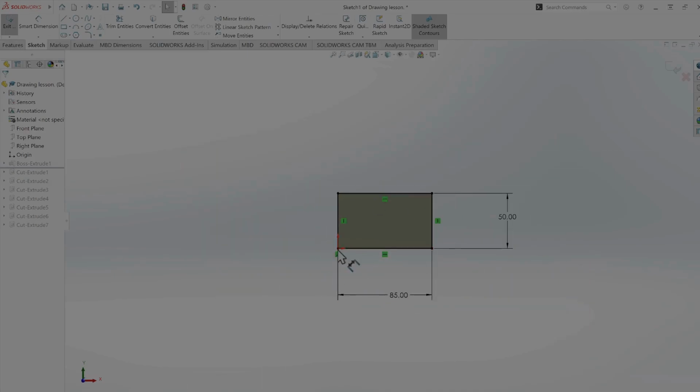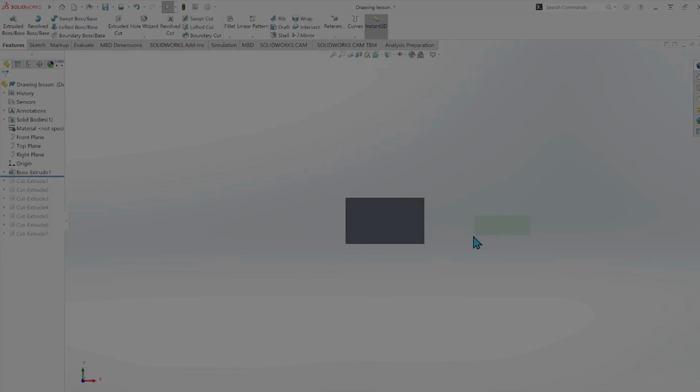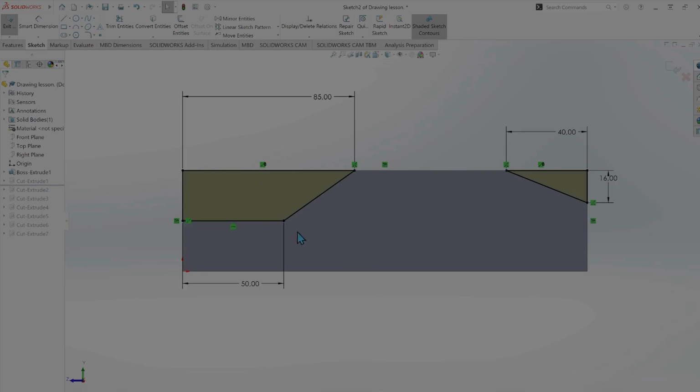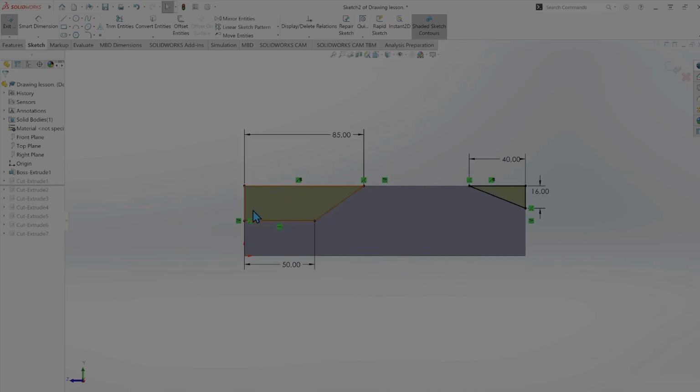So looking at it this way, you are pushing the object's shadow onto the wall behind it. And then in third angle projection, the shadow of the object falls onto the screen between you and the object.